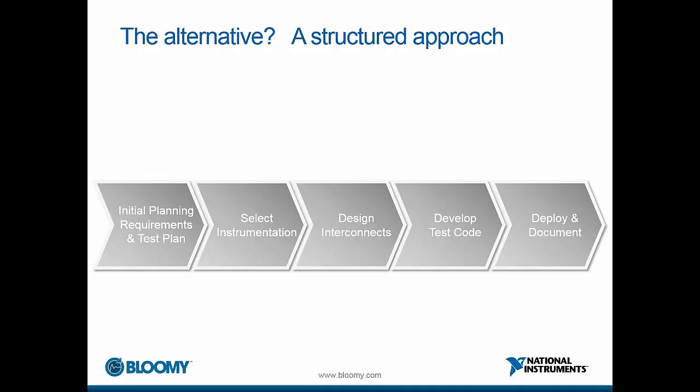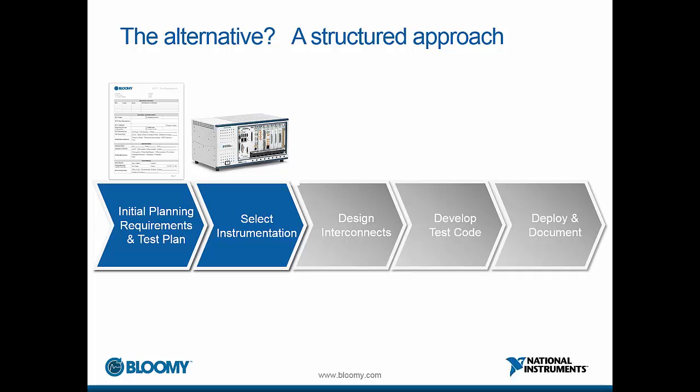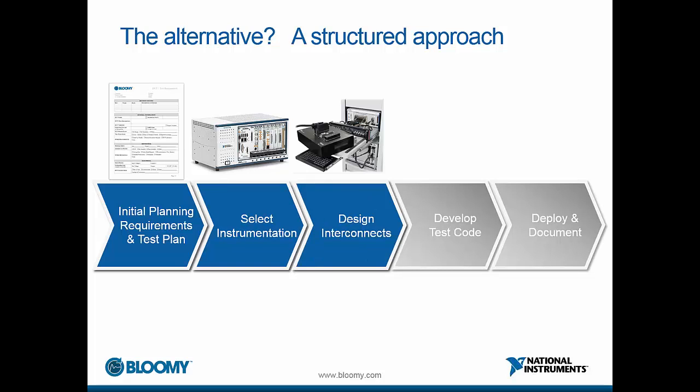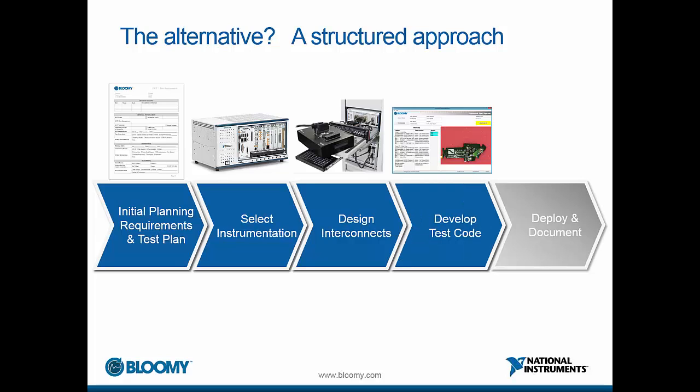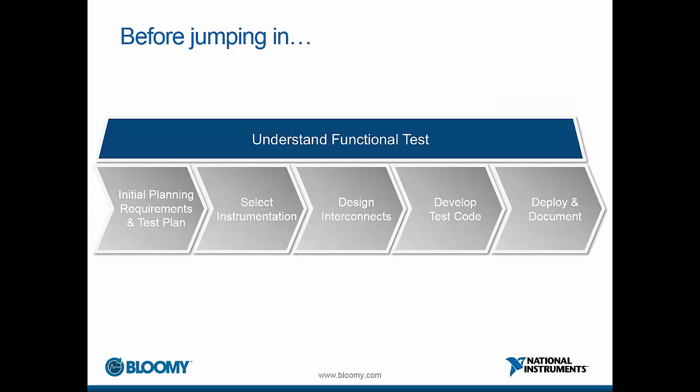Instead, let's take a look at a structured approach that we at Bloomy use when developing our ATE. It starts with the initial planning of our requirements and developing of a test procedure. Next, we select our instrumentation, such as PXI or boxed instruments. We then design the interconnects which will route that instrumentation to our unit under test, and we'll go over some best practices for developing our test sequences. Finally, we'll review some guidelines for deploying and documenting our system.